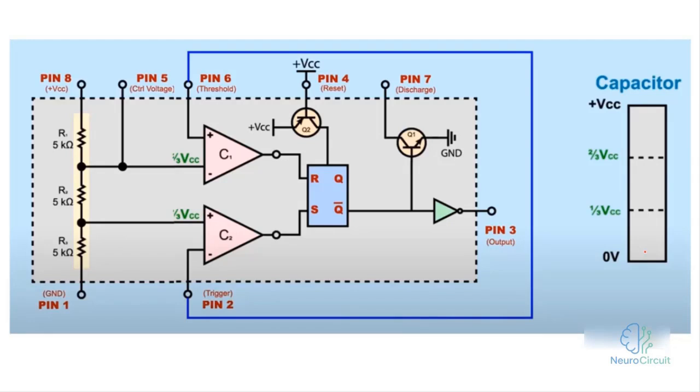Well, as we can see here, there's no button in this circuit because we don't need to apply any input to this part. I mentioned that in both the bistable and monostable modes, those buttons mean we're providing an input signal, but in the astable mode, we don't need to give any input. You saw its trigger in that first slide for the astable circuit. It was written as none, meaning we don't have a trigger or input signal.